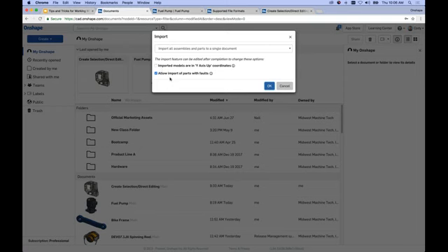Also, if you have any kind of issues with imports, there's a potential for a fault, meaning some kind of bad issue with geometry. You can allow imports with faults, and that's an option that's now on by default. It's been there for a while, but it's now on by default. These are a few import options that you'll want to reference. It helps for orienting the model. And then if you have any kind of geometry issues, it will allow those to translate and still be visible. And that's the important thing. In the past, if you imported geometry with errors, it wouldn't allow it. It would just fail to import.